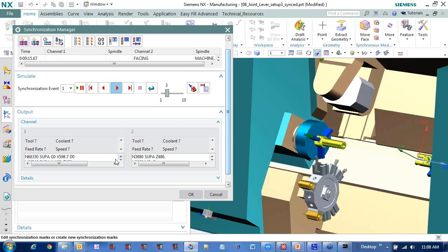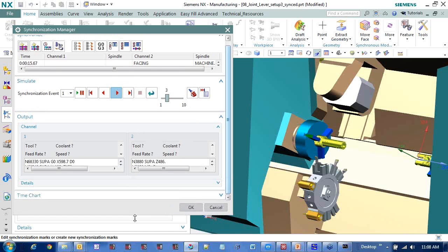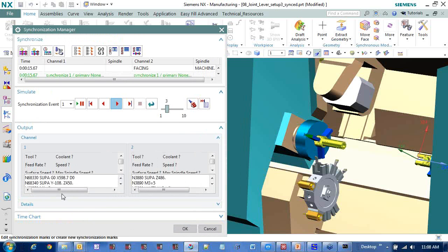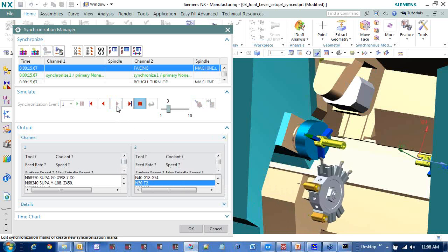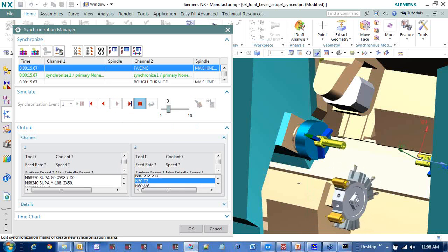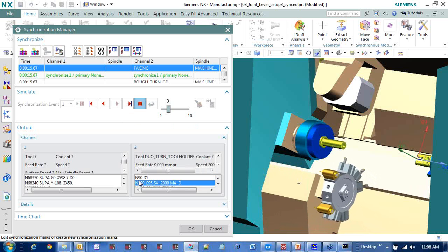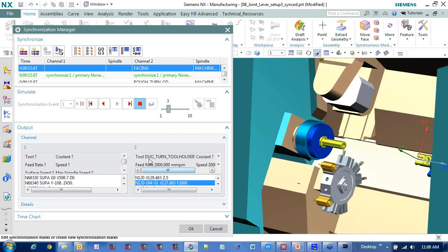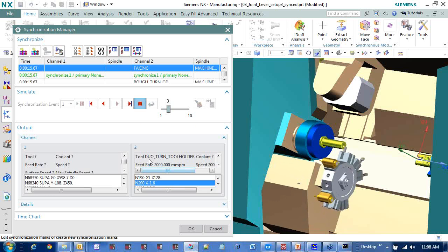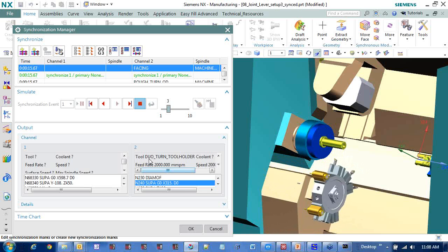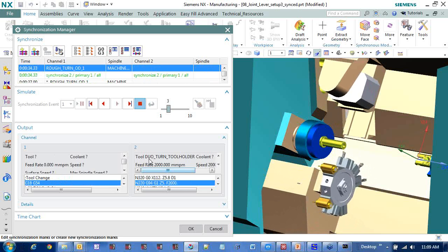is fairly complex. What we have here is our G-code output, and we have two channels. One channel drives the upper turret and one channel drives the lower turret, with synchronization code. So this is a real simulation. As you can see, things are wiggling around here, and you can see that it's switching channels. If you are familiar with this stuff, this is high-end stuff for doing verification. Maybe only one other verification software is capable of this.